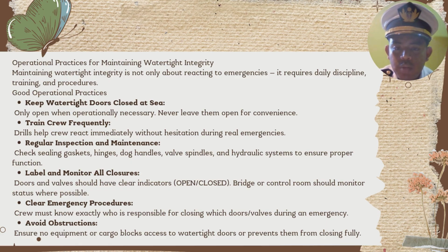Operational practice for maintaining watertight integrity. Maintaining watertight integrity is not only about reacting to emergency. It requires daily disciplines, training, and procedure. Good operational practice. First one is keep watertight door closed at sea. Only open when operationally necessary. Never leave them open for convenience.